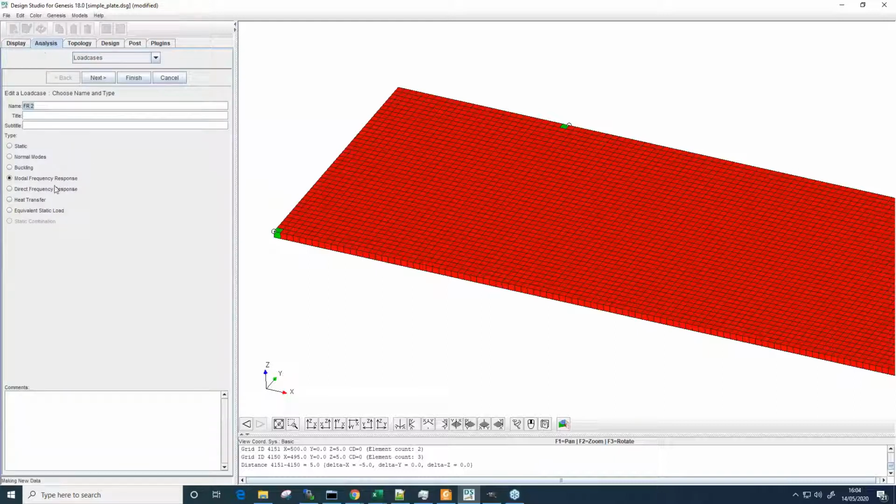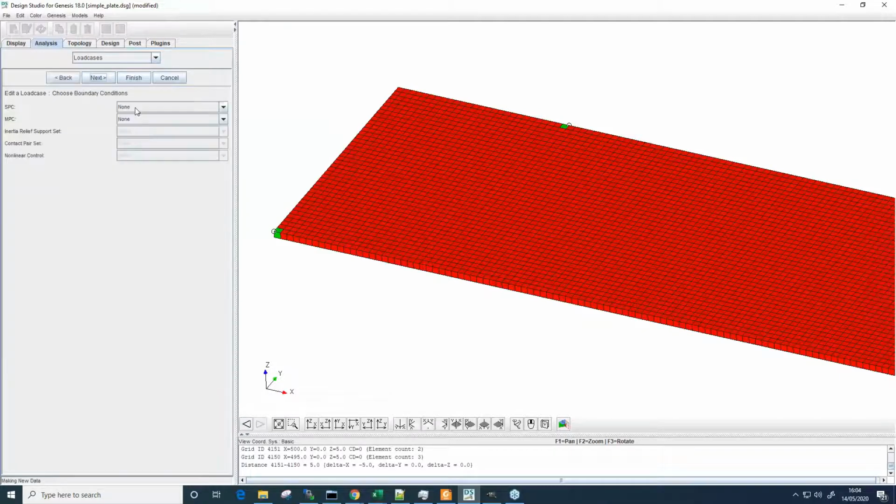If we look here, I'm going to do heat transfer. Give myself a load case. I'll do that thermal fixing, and I'll do my thermal load set. The output I can choose is to do my temperatures as a post-processing contour. So we'll do that first of all.